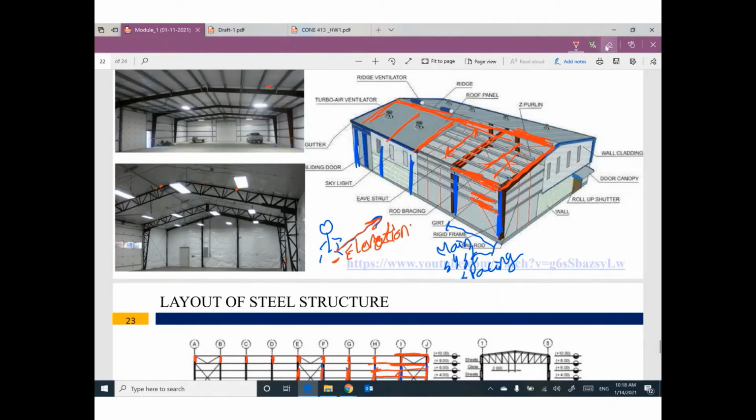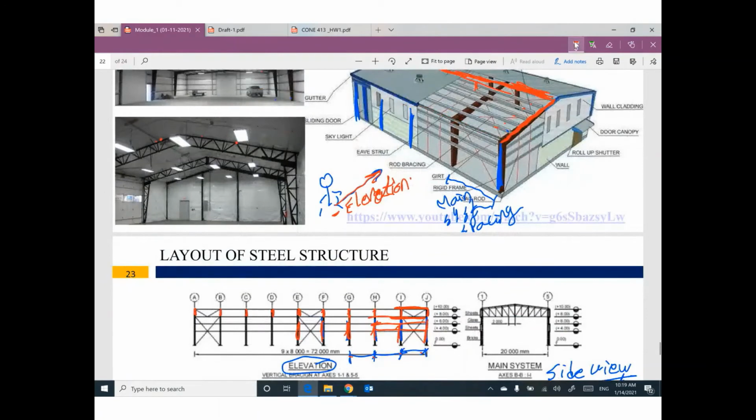And also keep in your mind, at the first panel I have vertical wind bracing. At the end I will have one also. Probably, if this distance is too long, I will have one at an intermediate location. That makes sense? That makes sense?